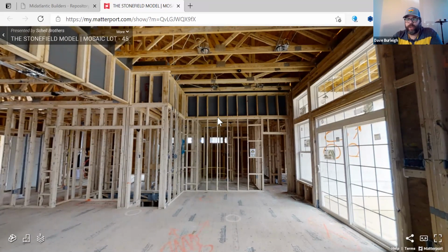Doesn't seem like a huge deal, but that's bottom and top plate that was not accounted for because we weren't planning on having two walls, as well as it altered what our stud counts were. Because I was no longer using these tall studs. I was using 9-foot studs and then filling in with cut pieces for that pony wall.